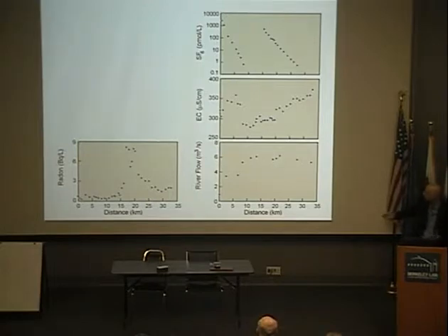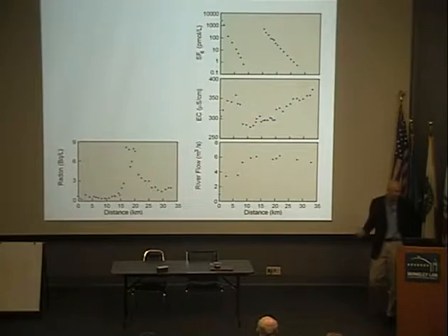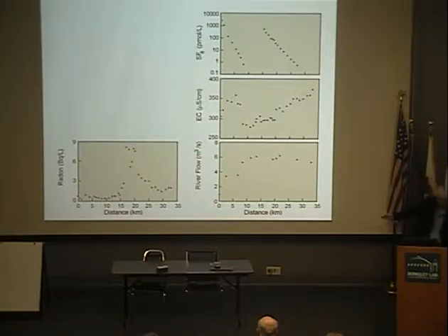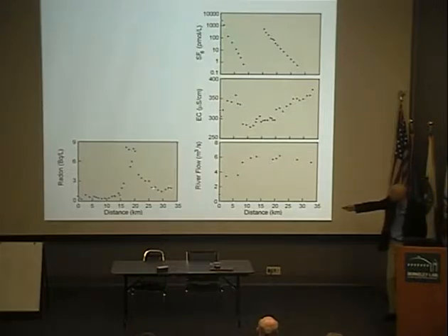So this is the radon concentrations I measured. This is now over a distance of about 33 kilometres. We've taken about a sample every kilometre. That took us about 2 days. And you can see relatively low radon concentrations here, large spike in radon in this zone here. Decrease below that, but it doesn't decrease to zero, indicating there's still some groundwater inflow in this area here.